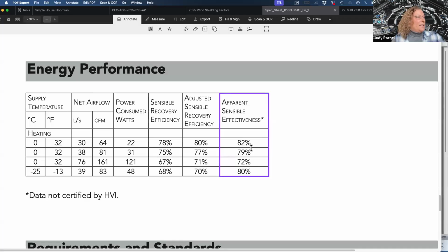Once again, this is a place where they don't give you that many choices. This is lower winter conditions than what Ventura would be subjected to. This is one place where I definitely would check the Title 24 documentation for the CFM it came up with. That's going to be the minimum that we're going to put in the house.